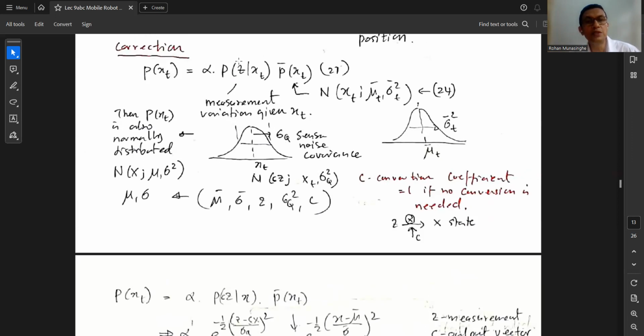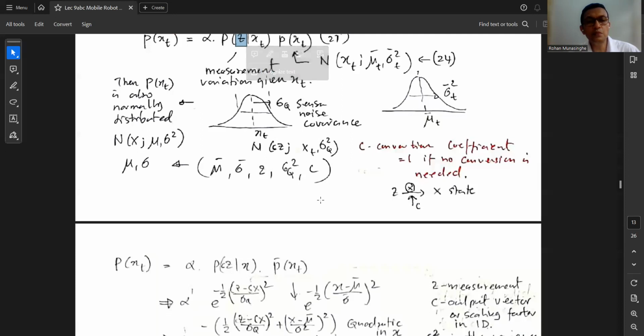And your measurement, as you know, in state space, the second equation is basically Z, right? The measurement is a combination of state variables, right? Z equals Cx. Sometimes we use variable Y instead of Z. But on the right-hand side, it is output matrix C times state vector X. So if there's any C, you have to put it over here, right? So this C should not be here. Z equals XC. So I will correct that. C has to go from here, right? It's not C Z, it's just Z.